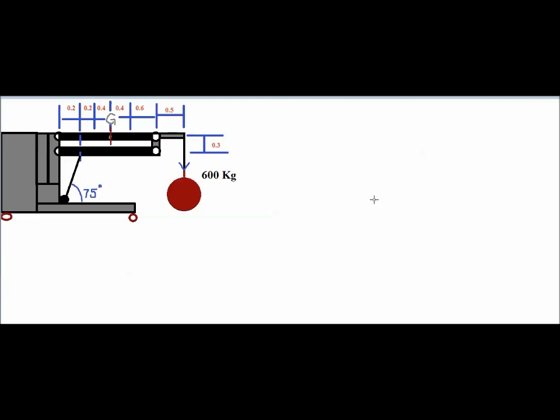The first one, of course, is whenever you have a reaction force which is unknown, even if you know the direction of these reaction forces, never ever apply the signs, because the sign will generate on its own in the equations. For example, this particular force over here is a reaction force, and I know that since the weight is acting downwards, this reaction has to act in the upward direction, so it would be something like that.